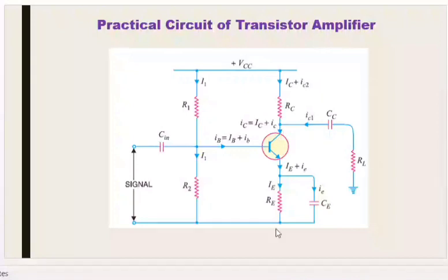Okay, so here resistance is very high, I mean RE. So if you are connecting CE with this circuit, the AC signal will flow through this capacitor. Here, if it were flowing through the resistance, what will happen? The voltage will drop, so we will not get the proper output. That's why we have connected the CE capacitor. It is connected in parallel to the RE. Is it clear why we have connected this capacitor in this part?